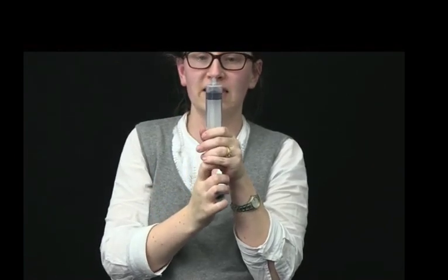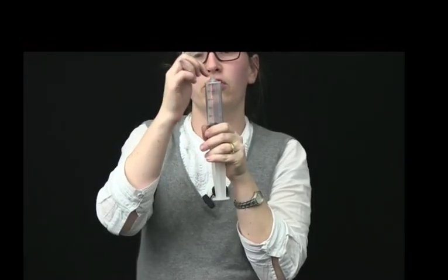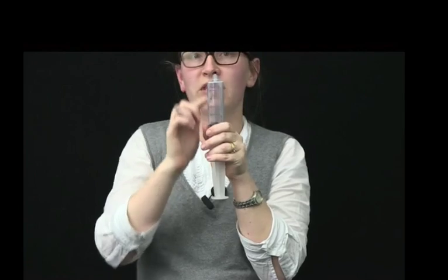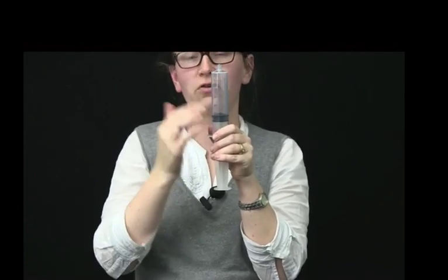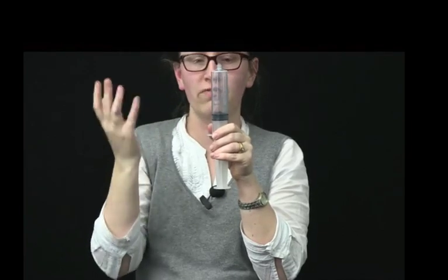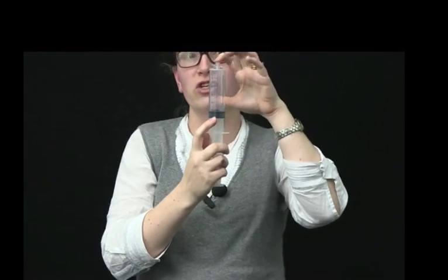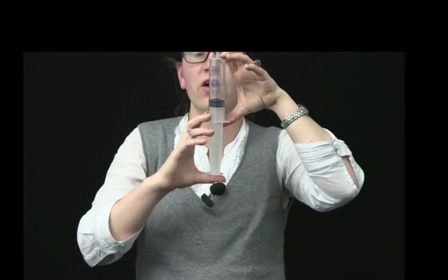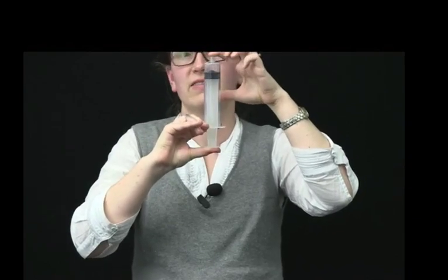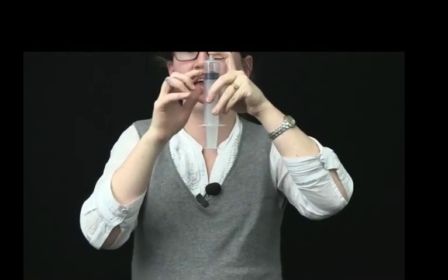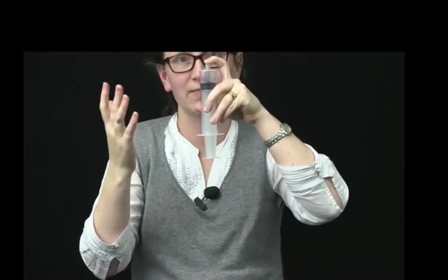so it pulls the piston down, and as it pulls the piston down, an air and fuel mixture goes in through this intake valve. So the cylinder in the car is now full of air with a mixture of the fuel in it as well. What happens then is that the intake valve is shut off and the engine does more work compressing this cylinder. So we've now got a mixture of fuel and air in there, which is all compressed.